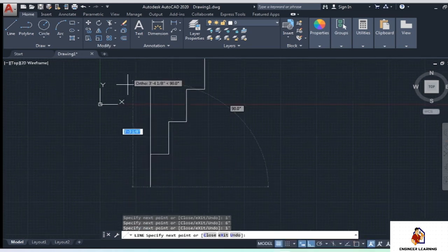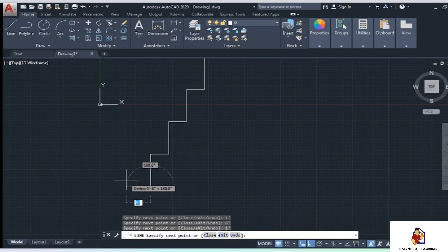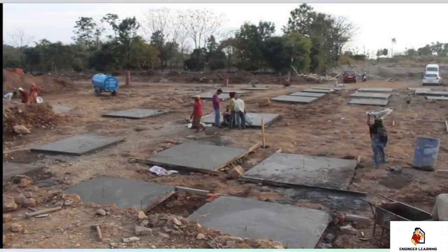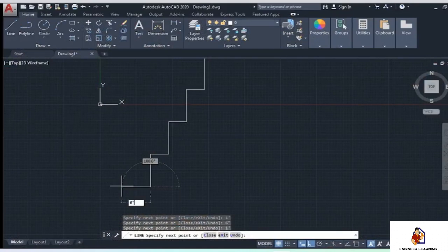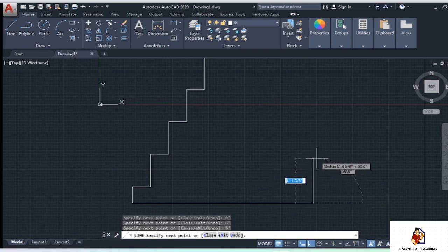Generally, the masonry footing depth is kept to 1 meter, slightly more than 3 feet. We have already reached a depth of 3 feet. Let's now form the PCC. PCC is provided to level the ground surface so that footing can be formed on it. Give it an offset of 6 inch and a depth of 6 inch. Move inside like this and enter a value of 5 feet: 2 feet for the offset and 1 feet for the column thickness.